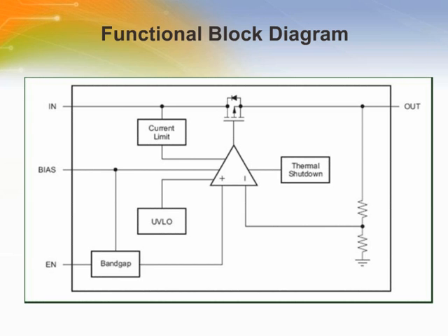The NMOS can have a low dropout voltage with a charge pump. The dropout voltage is determined by saturation voltage across the pass element, and the dropout voltage is proportional to the current flowing through the pass element. At light loads, the dropout voltage is only a few millivolts. At full loads, the typical dropout voltage is 350 millivolts.